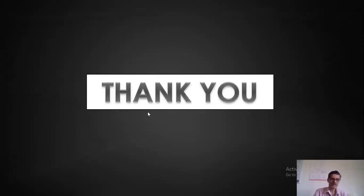So in this video, we discussed what SSB is, how to generate SSB using the frequency discrimination method, as well as the frequency spectrum representation, the time domain equation, and finally the advantages, disadvantages and applications of SSB.